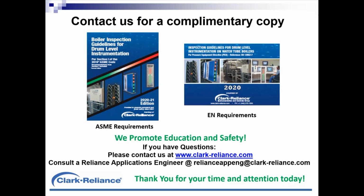Okay, thank you. There's a question here with no name: has anybody experienced a precipitous drop of about 5 inches and then recovered in drum level with steady or increasing feed water flow? That's an unusual one. We discussed that one earlier. What could be going on? I would be concerned about piping and making sure there's no restriction in any isolation valves or in the piping itself between the isolation valve and the drum.